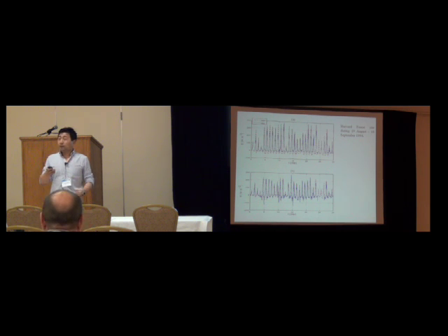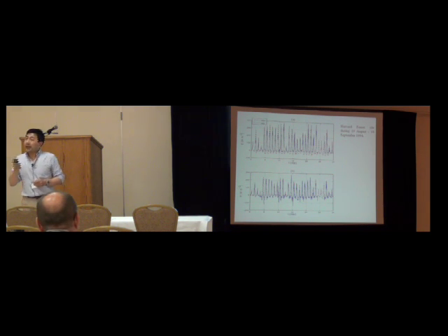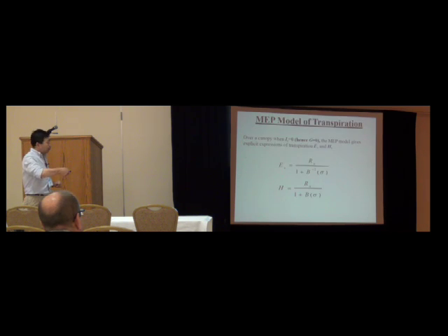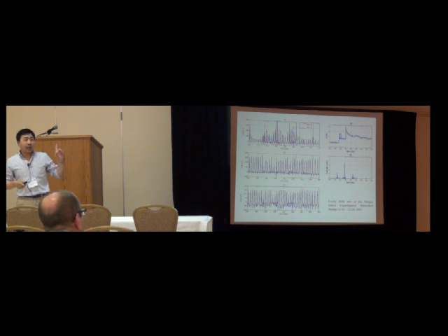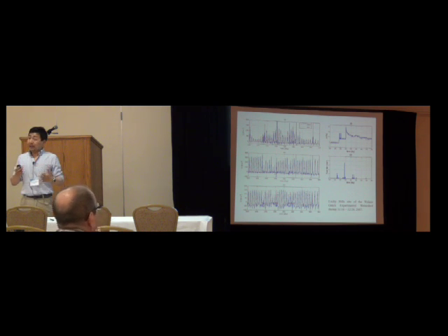Well, then you have a very nice testable prediction, do you not? That your MEP model is showing an appreciable negative flux at night. And that has to be measurable somehow. Yeah, exactly. Because at night, we know the net radiation is negative. So that negative radiation must go to either the sensible heat or ground heat, because at nighttime there is very little evaporation. We know that. And the ground heat flux in that case agrees a lot more closely than the other term.